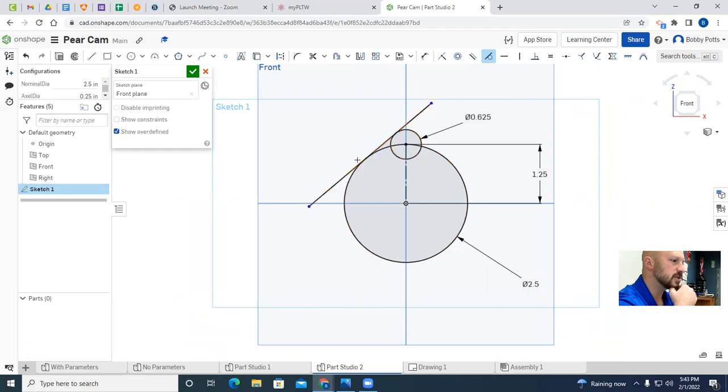Well, I want to do it again with the line and the big circle. So the reason I don't just connect it there and there is because that may constrain that line so that it's locked into a certain distance. But we want that line to expand and contract as I change these dimensions. We don't want it to be so rigid. It's got to be able to move.